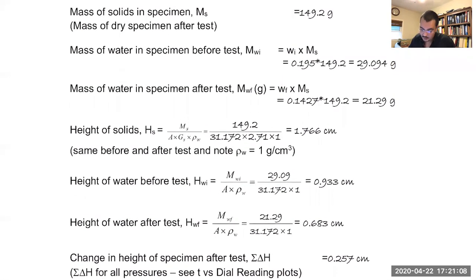Now for the height of solids, this is also a simple, straightforward equation. Here we have the mass of solids, we have the area of the sample, specific gravity, and unit weight of water. Oh no, sorry, density of water. So this is 1, and this is 1 gram per centimeter cubed. It's right here actually. And then you can find the height of solids, because you need the height of solids in your end graph, which will be the void ratio with the log pre-consolidation pressure.